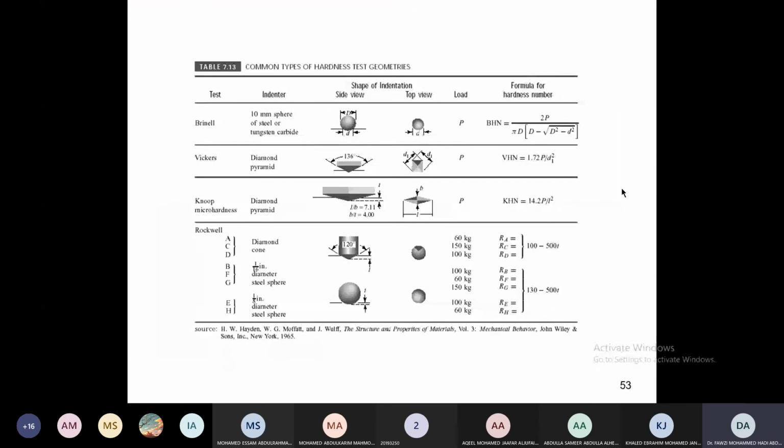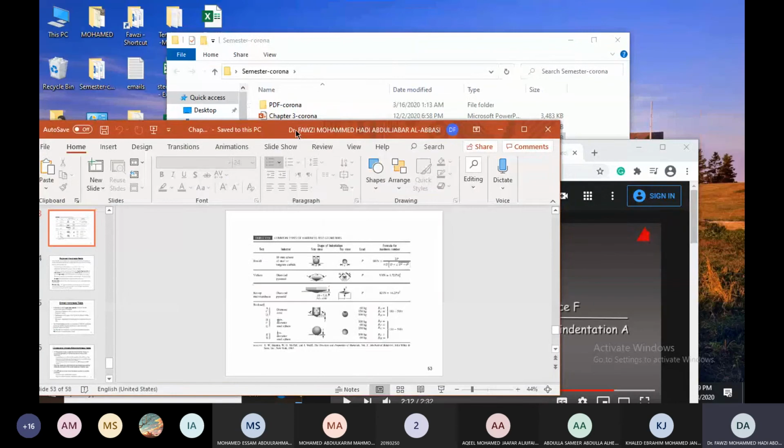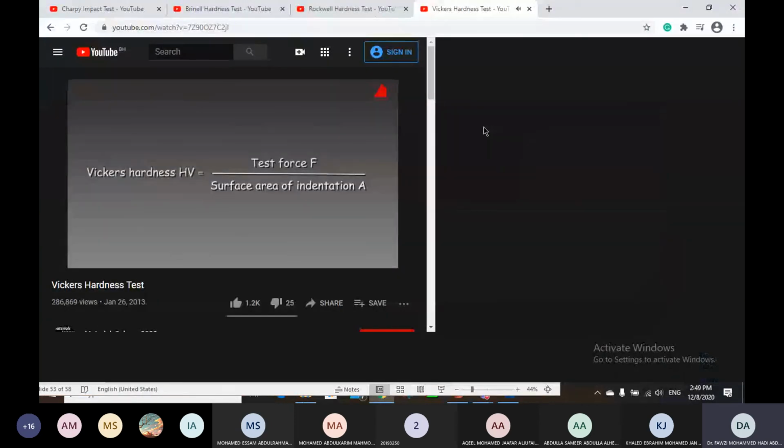We make it bigger. For the Vickers, this D is actually the average between that diagonal and this diagonal. It's never the area. That is the diagonal squared, the average diagonal squared. This number is also in the book here. It's wrong. It's 1.854 basically, and this table is wrong, and the correct number is given in your text. So it's not the area there as well. We have seen just in square millimeters.